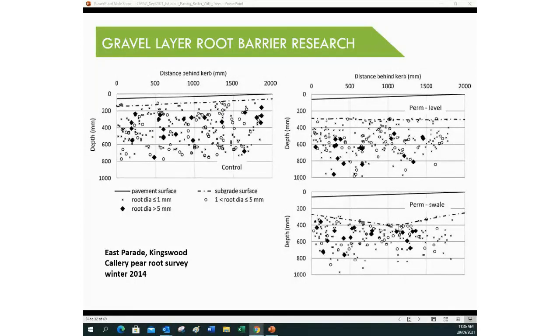Well, there's always surprises in research. We thought a bigger detention volume would harvest more water. No, it harvested less because 80% of Adelaide's rainfall falls at 4 millimetres an hour or less. So there's an optimum depth for soil moisture for trees versus dry soil for strength versus pavement base. A few factors to consider in here.